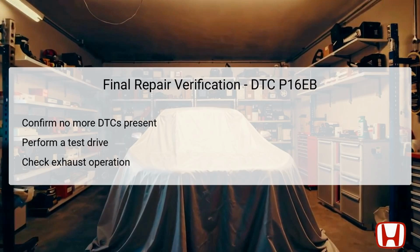functionality. After completing all necessary inspections and repairs, it is paramount to conduct a final verification of repairs associated with DTC P16EB. Start by re-scanning the vehicle system to ensure that no DTCs are present, especially those related to the active exhaust module and PCM.